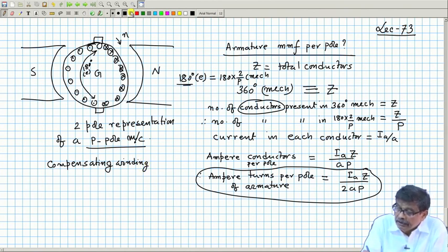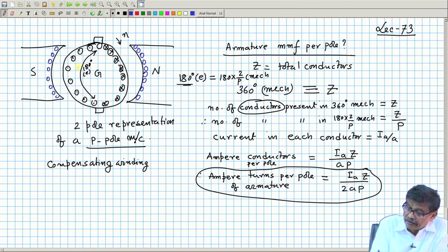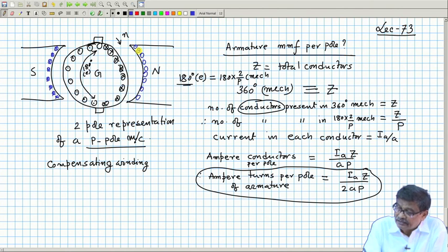These are the compensating conductors. I will make sure that the direction of the currents, if it is a dot, I will make it a cross, so that their effects will be nullified. We discussed last time from physical reasoning, because the air gap is small, you put this in close proximity, with the hope that the effect of these dot currents will nullify the effect of the cross currents.